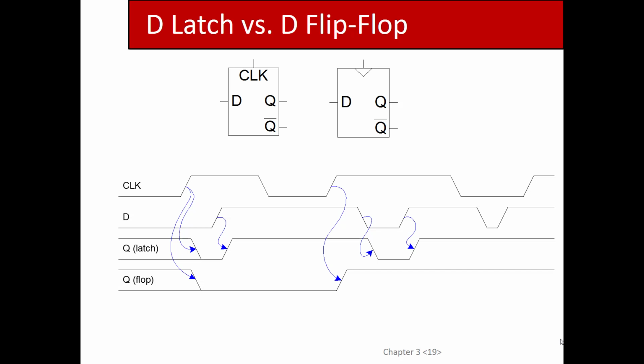The flip-flop drops here. It drops in response to the clock, right? So you look at the rising edge of the clock, and there is a corresponding drop in Q. Why? Because D was 0 at the time that the clock went up. Now D changes here after the rising edge of the clock. So there's a sequence. The first thing that happens is, well, D is initialized as 0. Then clock goes high. That triggers the output of the flop to go low.